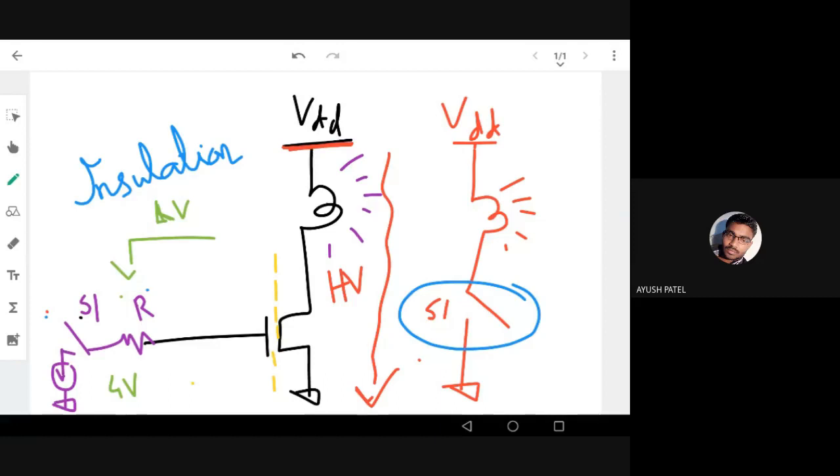Right. So this is another example. This system is very simple. Using a low voltage device, you are controlling a high voltage equipment. The same principle is used in relays. Relays are also the same principle. Here I'm using a transistor MOSFET for relaying a high voltage circuit or lamp or motor. The basic principle is the same, as given in the right part, of the simple switching mechanism, right?